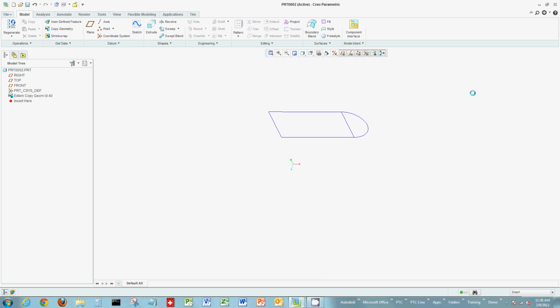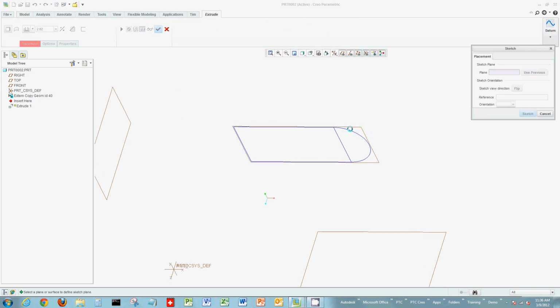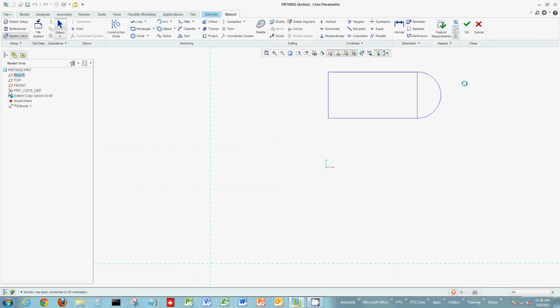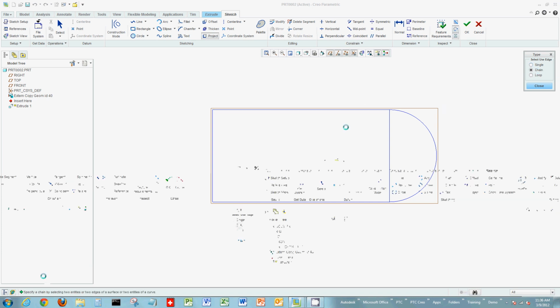And then once I have this in Creo Parametric, just based on this example here, I can start an extrude tool, in this case defining a sketch on this surface. And now what I can do is use existing geometry if I want in this example to create my new sketch. So maybe I'll just project, in this case, a chain.